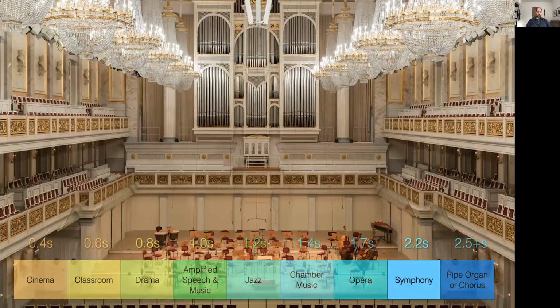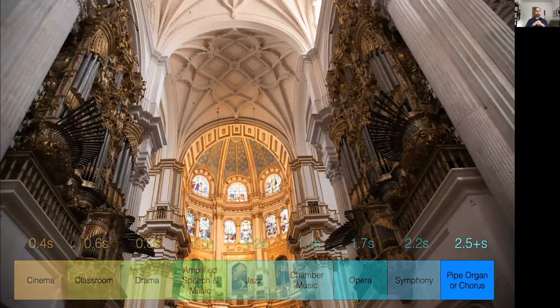And then over into the classical music world, now we're looking at a typical symphony hall. As you can see, it's a much larger volume and a lot less absorption. And the end result is a room that's roughly in the 1.8 to 2.2 seconds for classical symphony halls. And last but not least, we have large churches and cathedrals that start about around 2.5 seconds, can go all the way up to even 12 seconds. And that's due to, of course, the large volume and the lack of absorption, which, of course, they have a lot of stone, marble, glass, and whatnot, and that all contributes to having a long reverberation time.